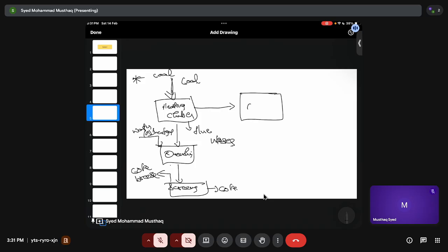Now what you try to do is you try to condense. A condenser is nothing but a very long tube, or you can have a helical tube. You are just increasing the surface area and taking the heat out, right? So once you condense, some may be volatile, some may not. Those which are not volatile, we will convert into liquids. So that is called tar, right? And again you cool it further, and then you do the distillation.